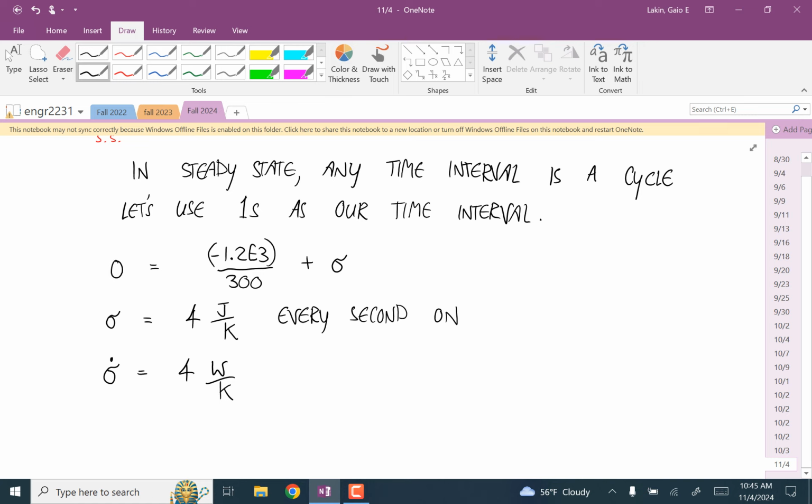Yeah. Heat is what always produces entropy, heat transfer. Remember, entropy is defined in terms of heat transfer across boundaries. And so every time heat goes from a high temperature location to a low temperature location, the usefulness of that energy is going down. And that's really what entropy production is. You're making energy less useful. Because we keep having to lower the temperature of the exhaust in order to get useful work out of it. Yep.